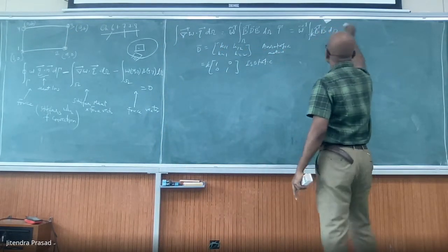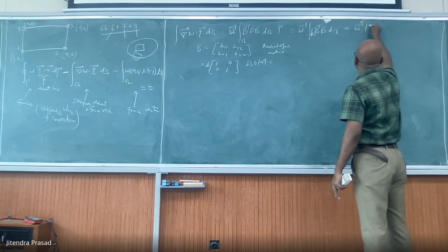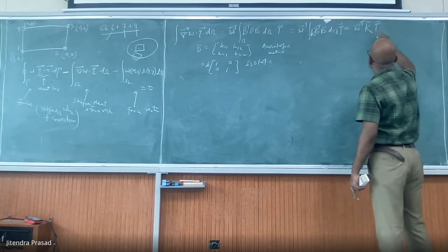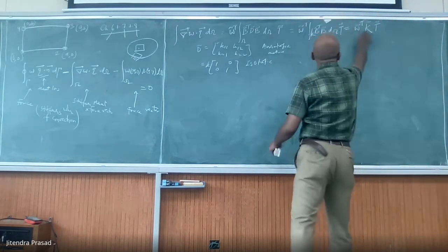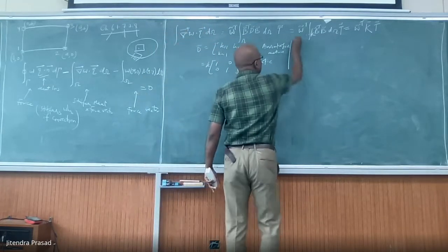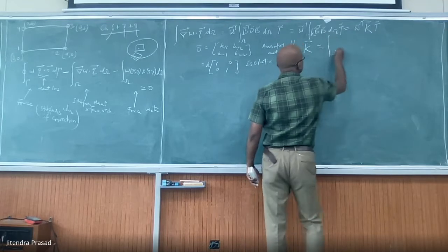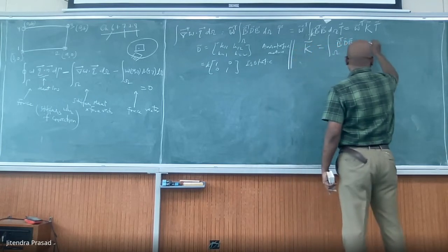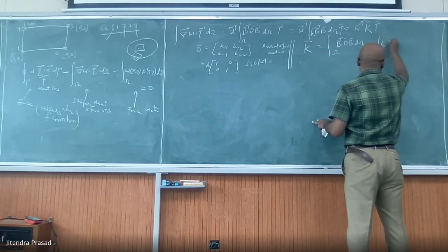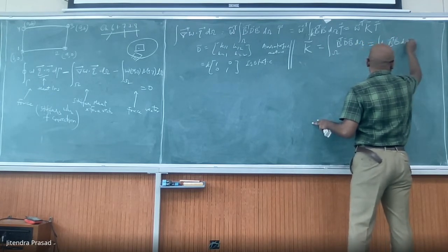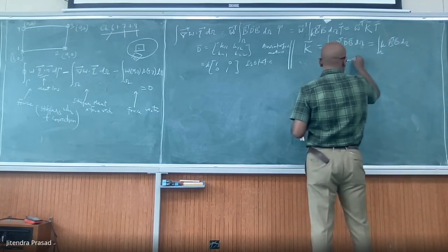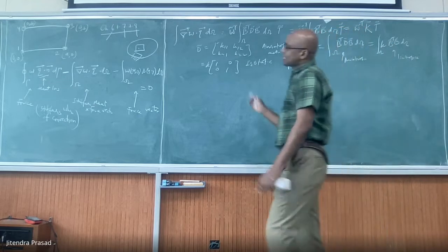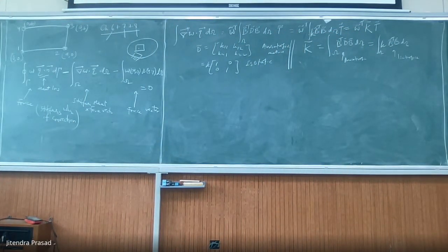This one we can write as transpose, this K. So this will be K and then T for the temperature vector. We know that K will be equal to the integral of B transpose D B in general, which is K times B transpose B d omega. So this is for isotropic; in general you can make it more general. We are just repeating this because it will repeat again and again. The only thing is the definition of B will change.